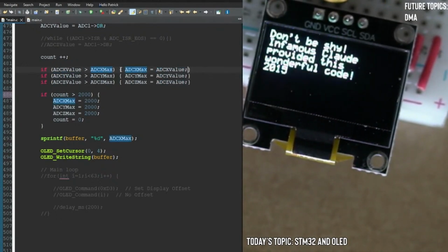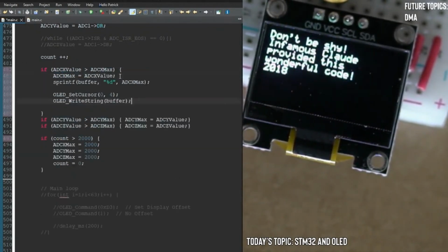So I'm going to put this on a new line because I think this is really slowing it down. Just this by itself, it takes a lot of clock cycles to do something. So I should see this climb up much faster now. So let's try that and see. Okay, yeah, look at that. You see how much faster that is? It's because this was taking up so many clock cycles.